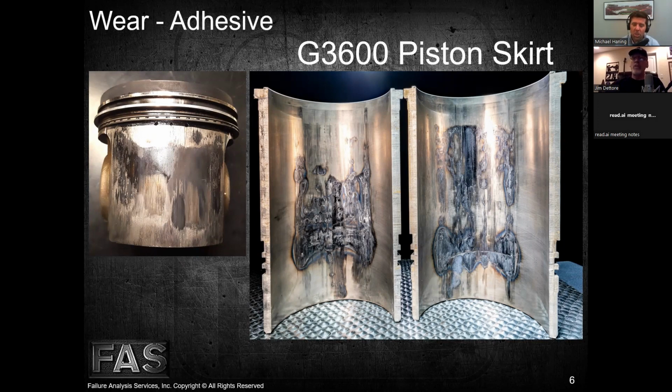So what's the normal operating temperature? In this case, this component should be running fairly close, maybe actual surface temperature just a little bit above engine oil temperature. Your engine oil temperature on these engines, talking with a lot of guys in the industry, they don't typically see in gas compression above 200 degrees Fahrenheit of the oil temperature. Now the piston crown temperatures can get significantly warmer, but we're also shooting oil at the bottom of that crown, helping to keep it cool.